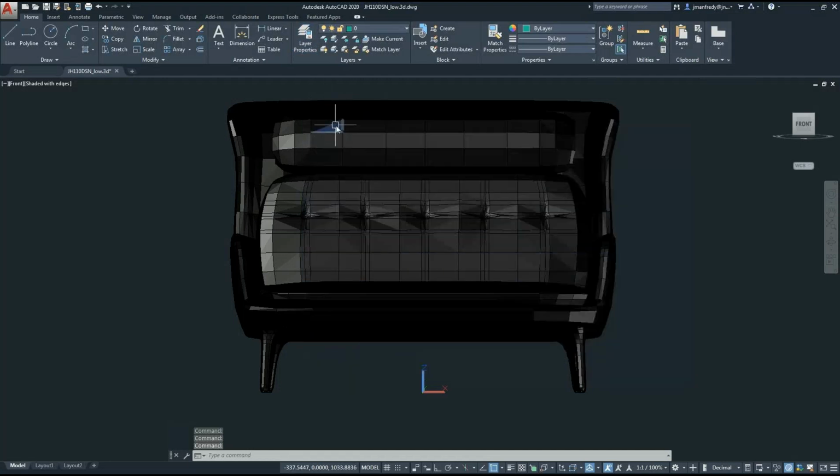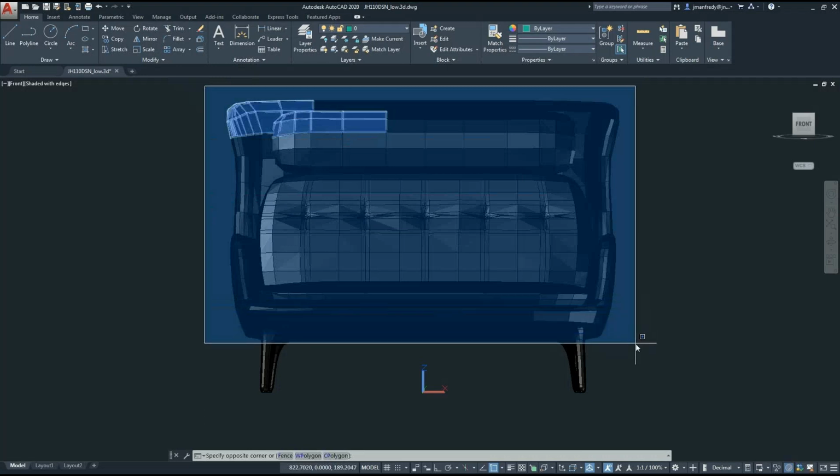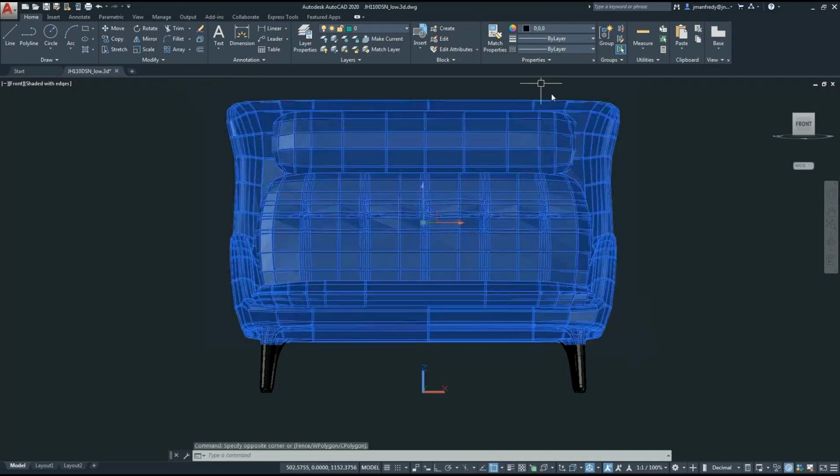And I will move these polygons into those layers so that they get translated correctly into Revit, and then I can manipulate those layers any which way I like in Revit in terms of assigning materials and changing the colors of the lines. So I will grab all these polygons here in AutoCAD. And then here, I'll simply convert those to the layer called 3D frame.